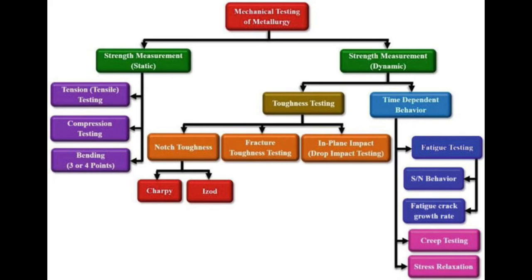Creep strain testing is performed by applying a constant tensile load to the test specimen and measuring the resulting strain. In order to determine the stress relaxation of a material, the specimen is deformed a given amount and the decrease in stress is recorded over a long period of exposure at constant elevated temperature. The stress relaxation rate is the slope of the curve at any point.